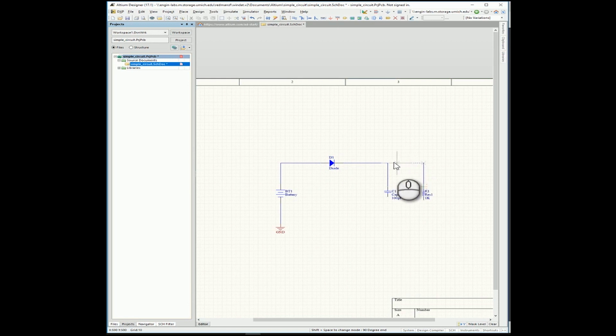And another thing you'll notice is that whenever we draw a circuit schematic, you want to use straight lines for your wires, and you want to move at right angles. Whenever you turn, you want to turn at right angles. And this is a convention you use when designing a lot of circuits to make things easily readable and understandable. So yeah, that's all of your components connected. You can see some nodes where your wires are intersecting. Everything looks good. So let's hit save,